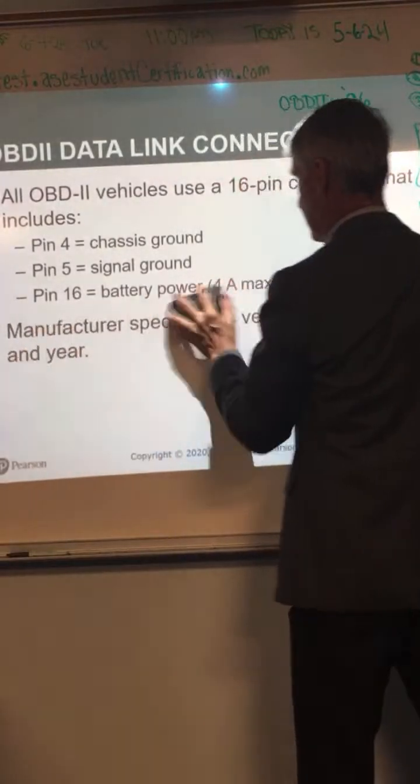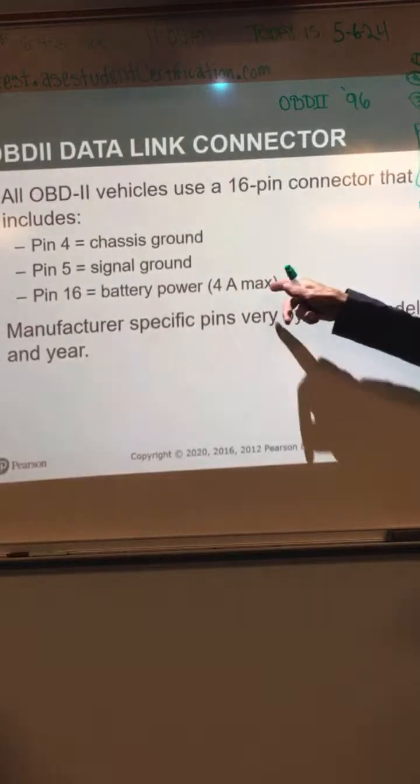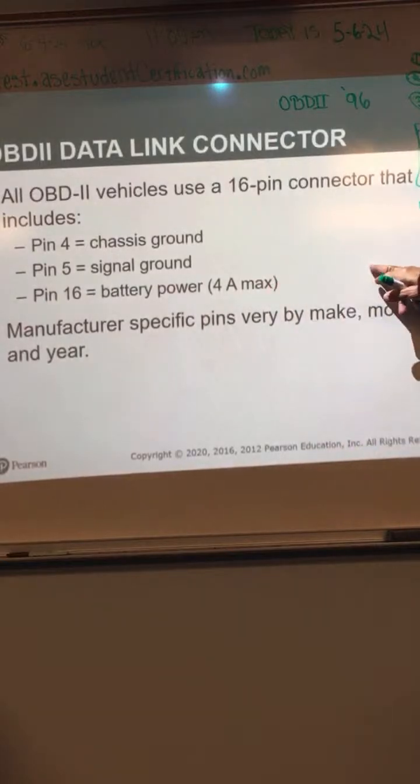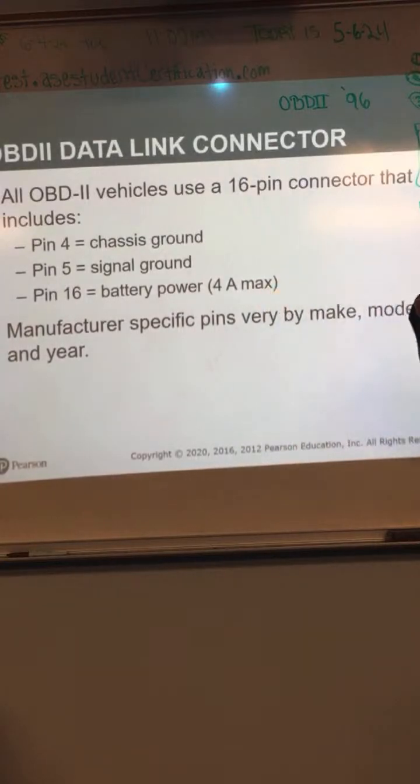Take a test light and probe pin 16 of the diagnostic connector. It's going to be the bottom one on the right, very last one, okay? With your test light grounded, that light should light. If it doesn't, the fuse that powers that's probably blown.